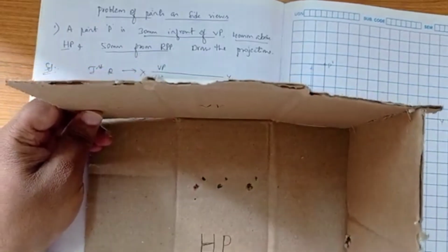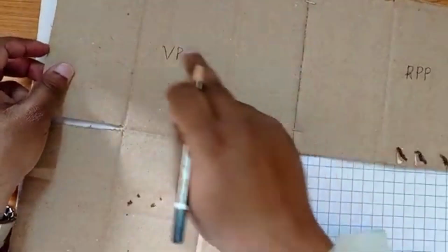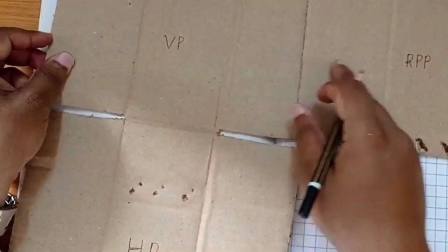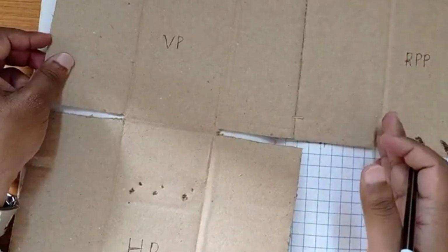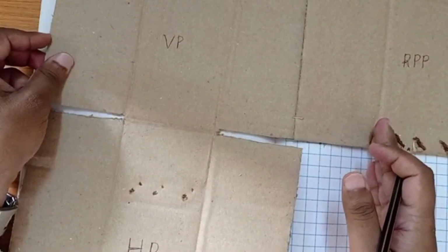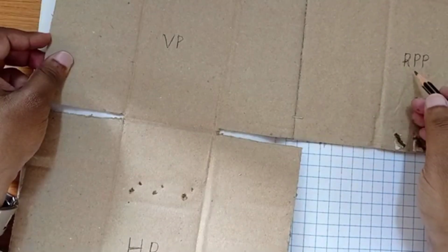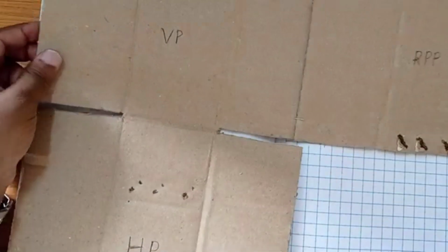Okay, when it is drawn in orthographic, it will be like this. The front view and top view, with the front view connected to the side view. So for this RPP we will be drawing another x1 y1 line at a distance of 50 mm. To connect the side view with the top view we will be using a 45-degree angle line. Just follow the procedure.